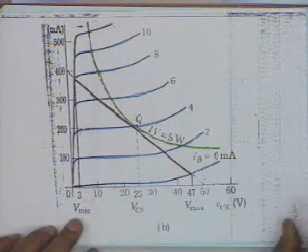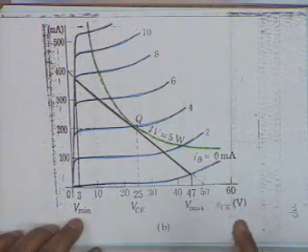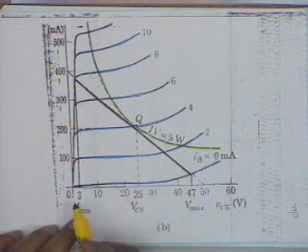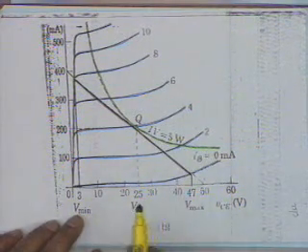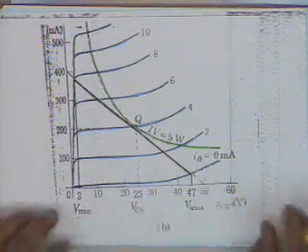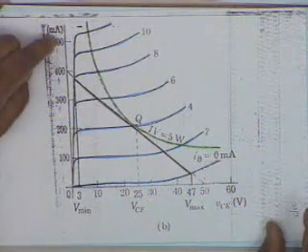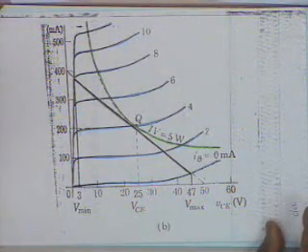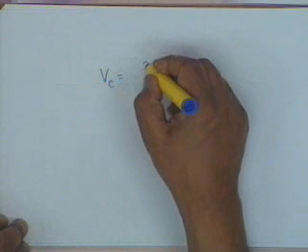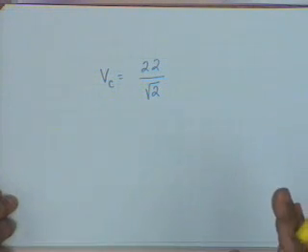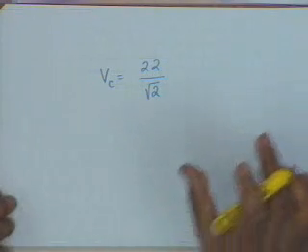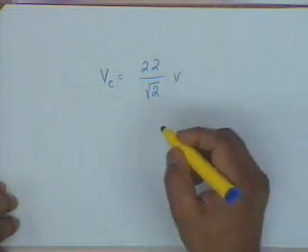All right. And therefore, the root mean squared value of the output signal can be 47 minus 3, that is 44, divided by 2, that is the peak value, 22, and the root mean squared value shall be 22 divided by root 2. Is that clear? We are not taking the current into consideration. Why? Because we are not going to the maximum possible current swing. So, my root mean squared value of the load voltage V sub C shall be 22 divided by root 2. Do all of you understand why it is 22 by root 2? Maximum V minus minimum divided by 2 is the peak value. Peak value divided by root 2 is this.